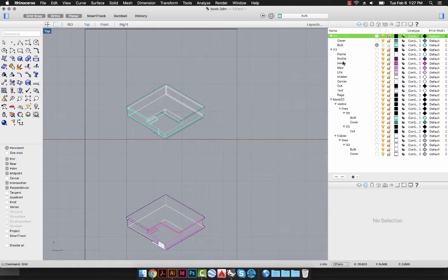It's just very simple. And then under my 2D layers, I have all these sub layers, and those are going to be the layers that are exported to Illustrator. And in Illustrator, I can use those layer names to go ahead and assign line weights. And we automatically know that poche is the heaviest, and my light or hidden lines would be some of the lighter lines.